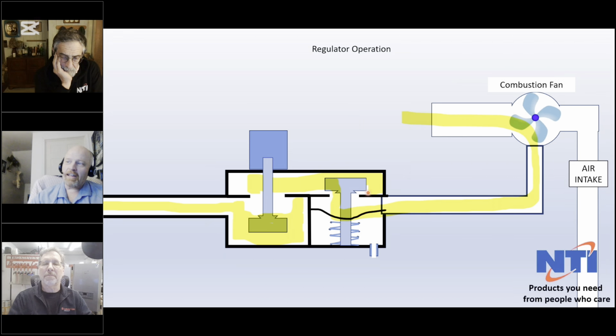There's the big rubber diaphragm we talked about. This little brass hole or ferrule here is actually connected up to the regulator. And so that feedback line that I talked about before actually passes through this brass. And I'll say it pulls on the bottom of this diaphragm. And our gas line connection's over here. And then of course the solenoid at the top.